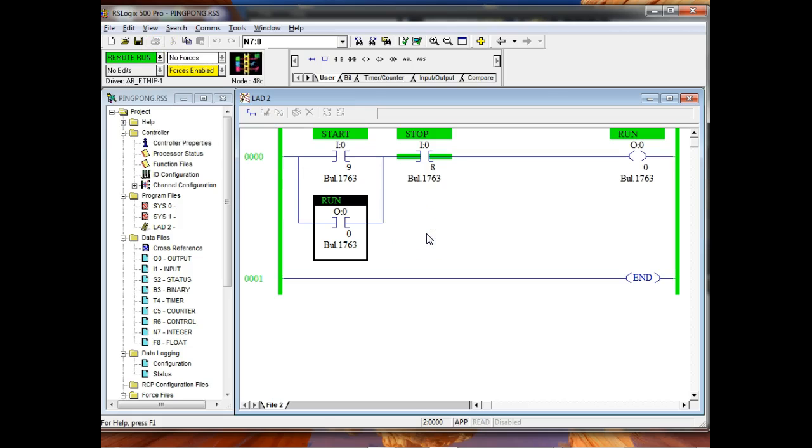And now it shows us what? Shows it's true. So now I can hit my start button, right? And it does what? I might need to hook up the motor so I can hear it, but you can see the output. And I come over here to the stop button, it does what? Stops it, right? I hit the stop button and the wire breaks. What did it do? The motor stopped, right? So this gives people some problems. We do have a little problem on the 1000s.